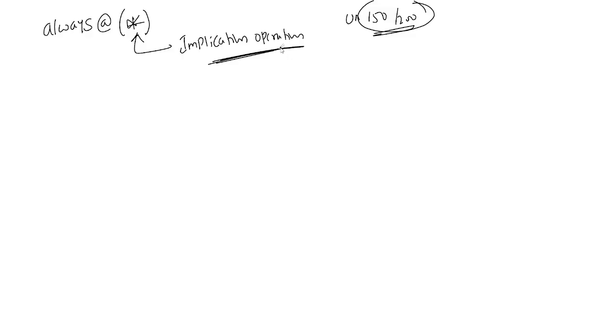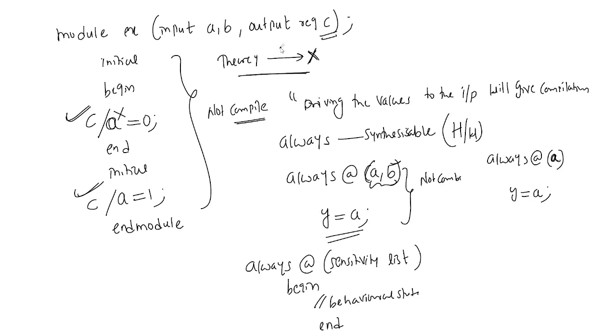So this part I did not understand completely. When you say if there is a change in the input, there is a change in the output, and that I need to give in the sensitivity list. Does it mean that, for example, in my code all the inputs are used, but some of them may not cause the output change? Then I will not use them here. Means you need to indicate all the inputs only.